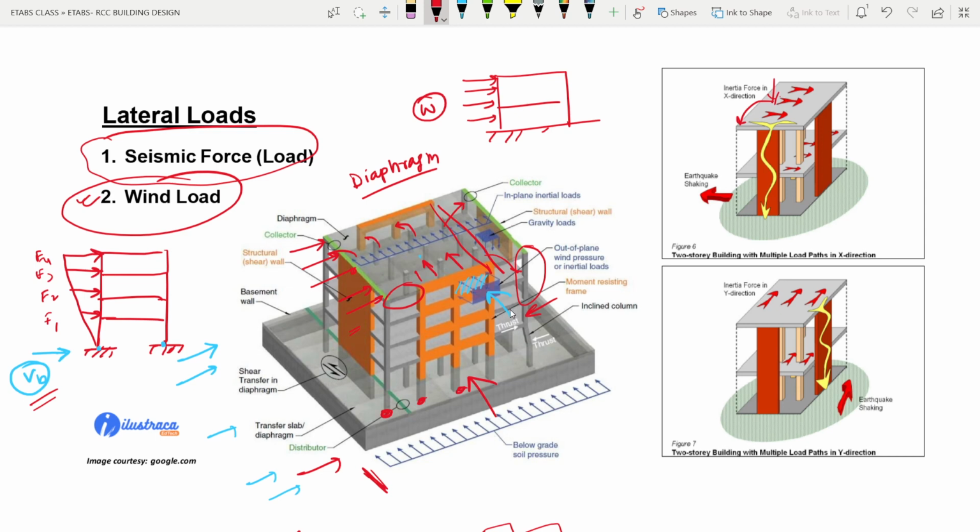So you will see that the tendency of failure in this kind of structure is more than in structures with beams and columns. And in structures with beams and columns, suppose these are the beams and these are the columns, the connections between these beams and columns are actually rigid connections. So if the horizontal and vertical members are connected with rigid connections and create this kind of frame, we call this kind of structure a frame structure.